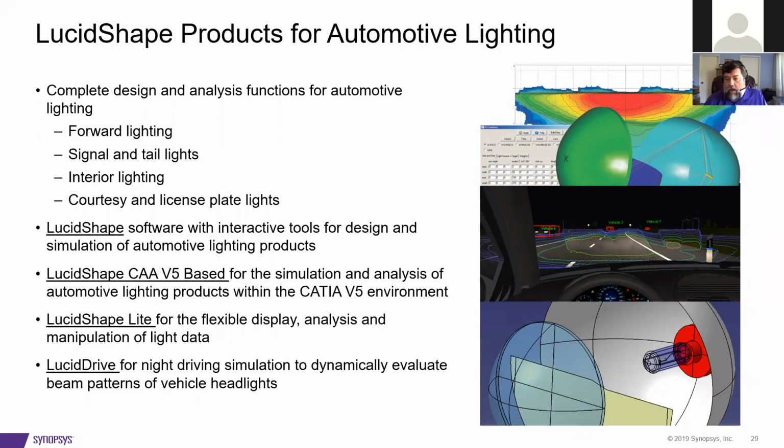which is very good for especially the latest generation of headlights, which are what they call pixel light displays or active displays, where you're basically on high beam. The car detects another car coming. It then dims that region, not the whole region, but just the region around the car. It tracks the car as the car goes by so that you don't blind that driver, but everywhere else is lit. These are on high-end cars right now. I expect you'll see them on every car at some point, or on many cars anyway.